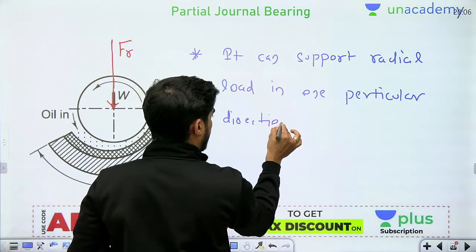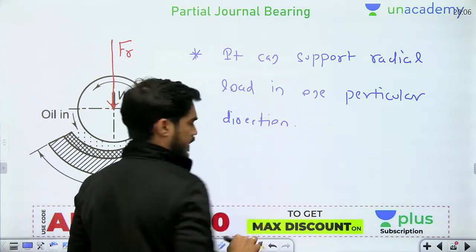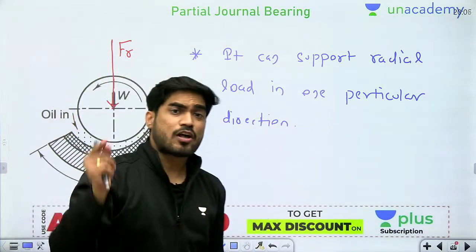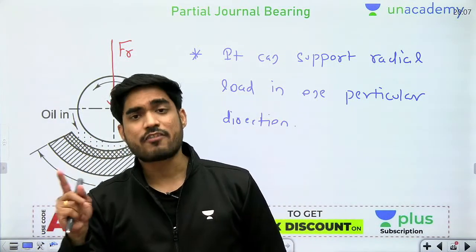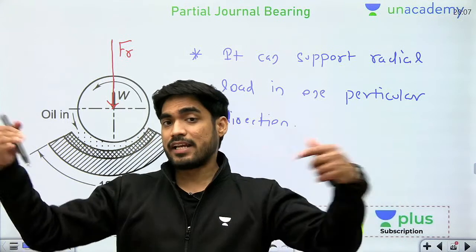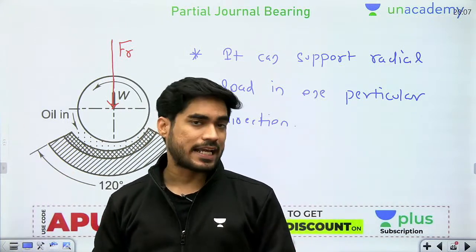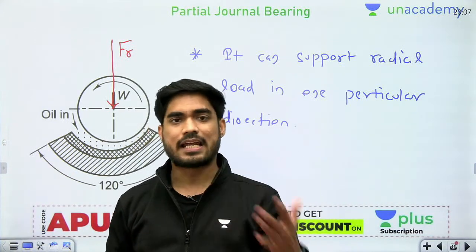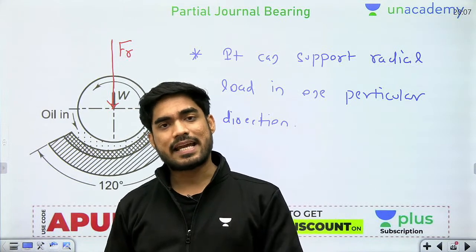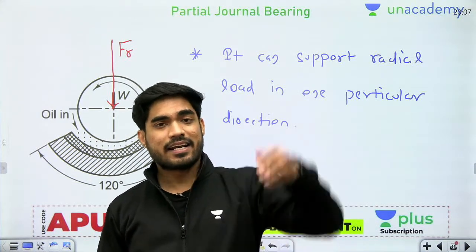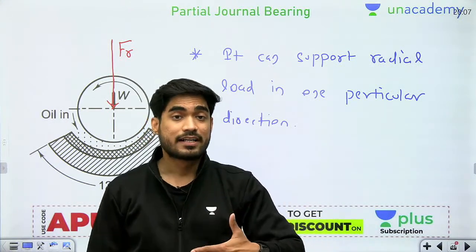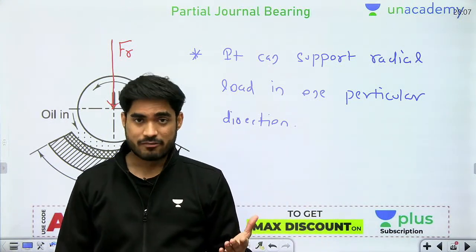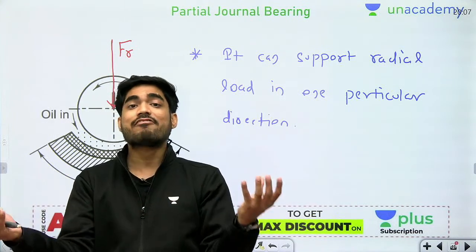In which case you will get radial load only in one direction. So understand, in case of axles, there is radial load only in one direction. In case of shafts, load can be in any direction. Shaft के case में the radial load can be in any direction. But beta, in case of axles, the radial load is only vertical direction. Axle means which is not transferring the power, which is only there to support the wheels.